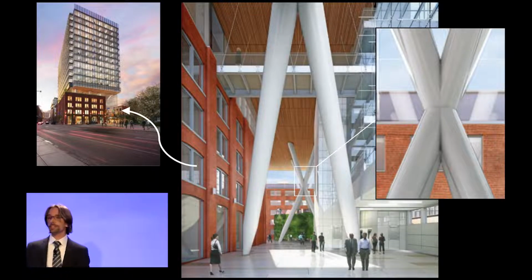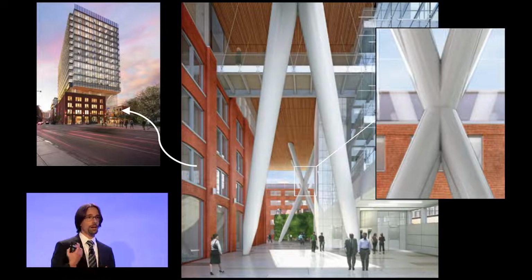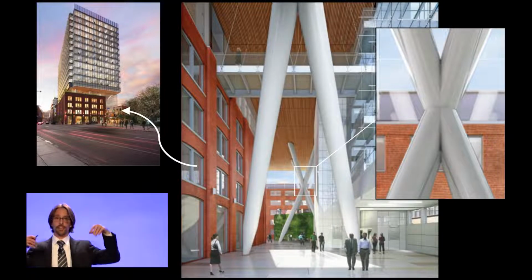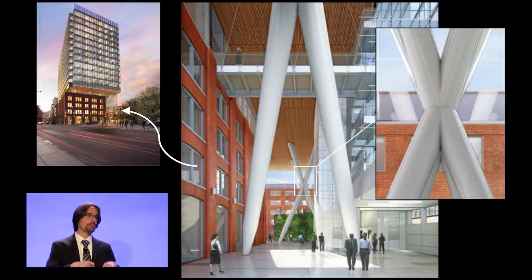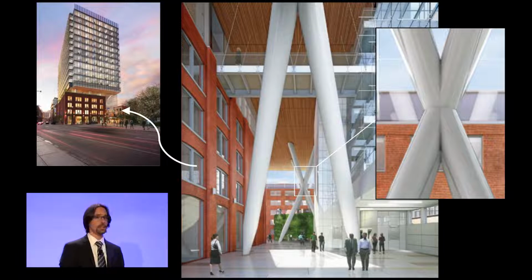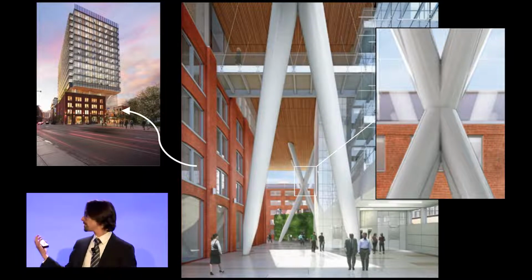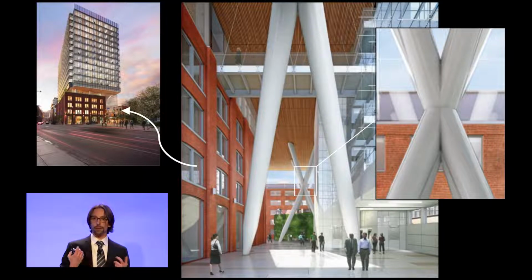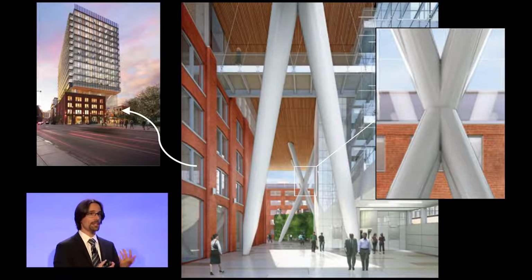The frames themselves were shaped for structural performance. They're part of the lateral system of the building above. So when the wind blows on that building above, those forces have to go through those frames, the lateral forces. And in addition, obviously, there's just a huge amount of gravity load going through those structural elements. So they're very much structure. But if you look at their shaping, they're also a form of art. When you go into that space, you forget that they're structure. They're part of the architectural aesthetic of that space.